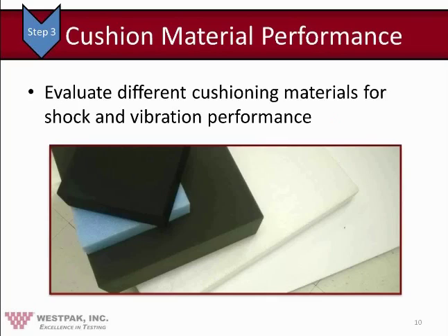Next step, step 3, is cushion material performance. When you're looking at cushion material, you're definitely trying to quantify something. More specifically, when you're quantifying shock performance, it means that you're seeing what the response of your unit is after you drop your product on this cushion. And secondly, when you quantify vibration performance, it means the amplification and attenuation plots of what gets charted on your resonant frequency.